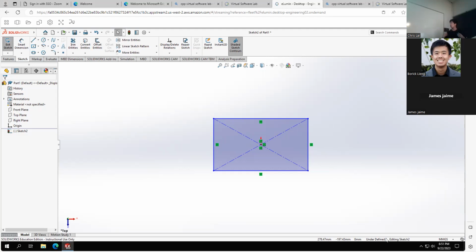It's generally always good practice to have your sketch be fully defined, right? Because let's say you are making this in industry, and you're drawing your sketches, and it's not defined. It's possible that the sketch could change its dimension when you're clicking around. That would be bad. And you also want the person looking at your 3D model or sketches to understand what's going on.